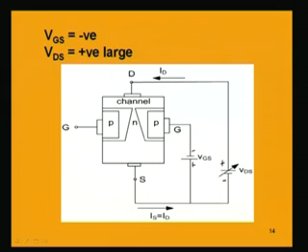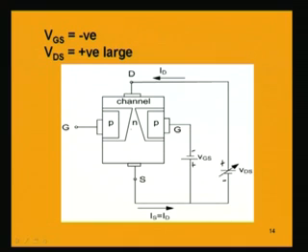But then if we go on increasing the VDS to a high value, the n channel between these two P's will have a change in its width, because one phenomenon which is happening here is that the depletion region present in the PN diode, that is in between the PN materials, this depletion region is dependent upon what? Upon the reverse biasing voltage.